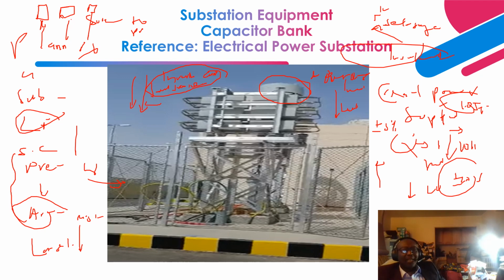One of them is utilizing resistors in series to limit the amount of inrush current. There are other devices, called controlled switching, that measure the sinusoidal wave and determine the actual point on the sinusoidal wave to energize the capacitor bank to mitigate or limit the inrush current that occurs during energization of the capacitor bank.